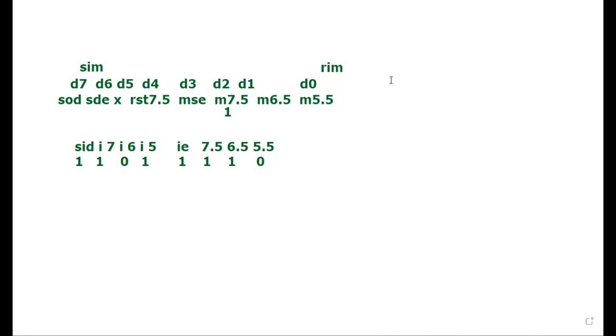Then you have two more instructions, NOP and halt. Okay, no operation, it doesn't do anything. Halt, it takes the microprocessor into wait state. You have to press the reset key after the halt instruction. Then there are two more interrupt related instruction, EI and DI, right? Enable interrupt and disable interrupt. Interrupt related instructions, stack related instruction, machine related instructions, and input output related instruction come under a machine control group of instructions.